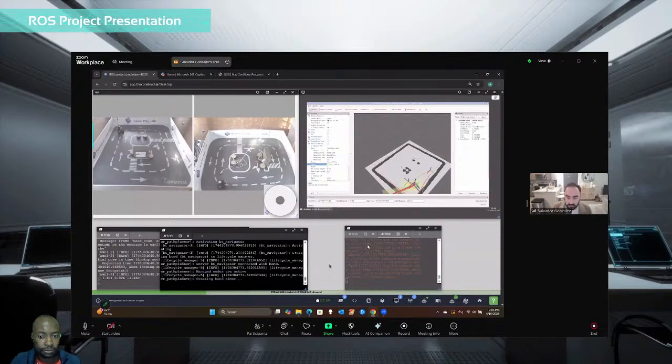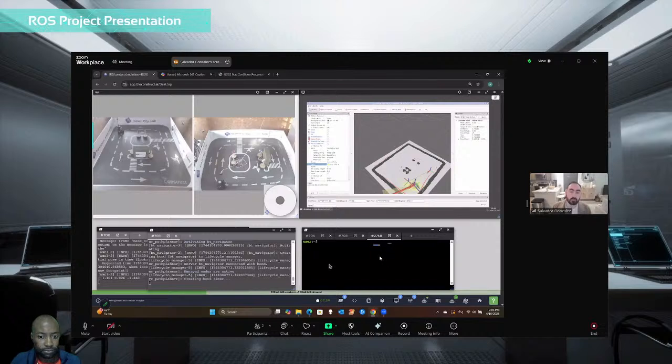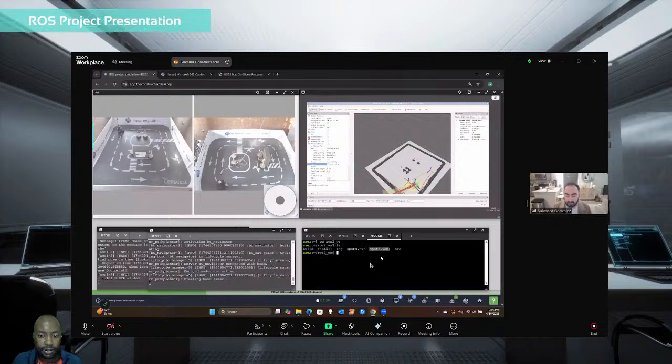We can see here that's this guy here. I'm sorry, not my map. The spots that I want to go to. So this is what I've named the file, and that's where I'm going to go. So what I'm going to do is ROS2 run. The package it's in is project pathfinding planning, and the name of the executable that I've made is called movex. And then I'm going to give it the name of the point. We have the 3 points, which is corner 1, pedestrian, and corner 2. And I'm going to give it a command, and then we'll see how it does.